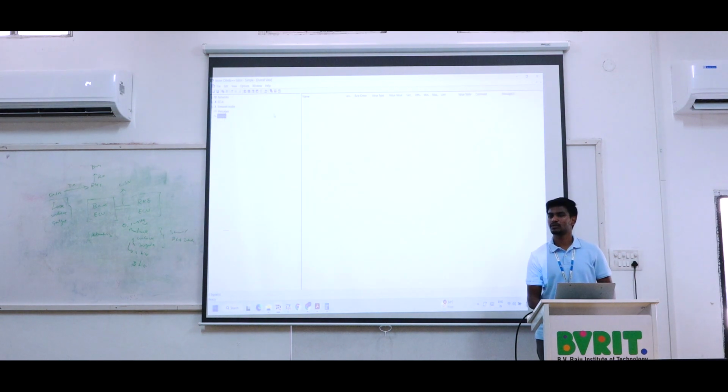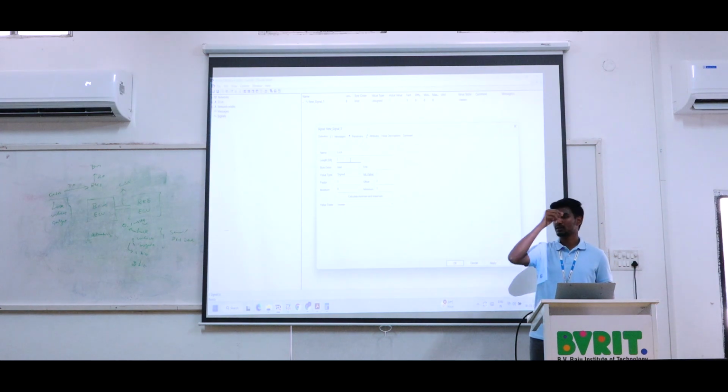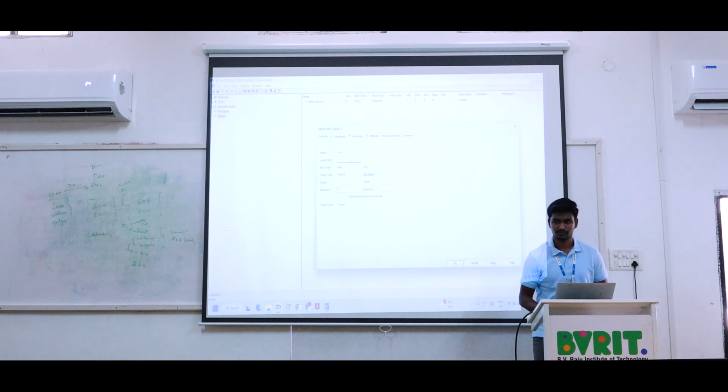Here we are going to create the signals and then we will allocate the ID numbers. Right click and then give New. This is the definition of the signals. In that we need to create a signal name. Based on the length in bits we need, we can change the length. These signals we have already created, so I just give the overview and mention some of the shortcuts. Instead of going to consistency check, we will get some key points using this.